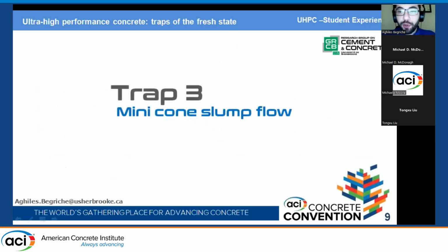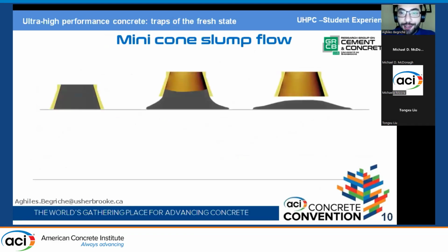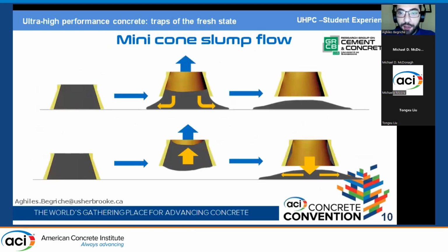Concerning the slump flow test manipulation, the normal standard test must be conducted as it's presented at the top of the figure, and not like in the second part of the picture. The factor which can impact the quality of the test is the time we take between the filling of the mini cone molds and its bring up.